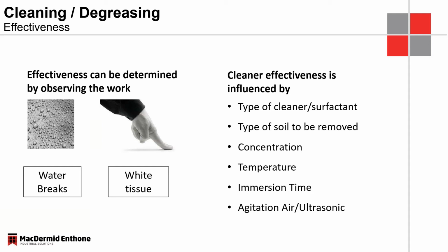The effectiveness of a cleaner, I just touched on it. It really depends on the type of soil we want to remove. So not every cleaner will be effective for every residue, every oil, grease, polishing compound that needs to be removed. So there's a few tests that need to be done prior to installing these cleaners. Obviously, concentration.